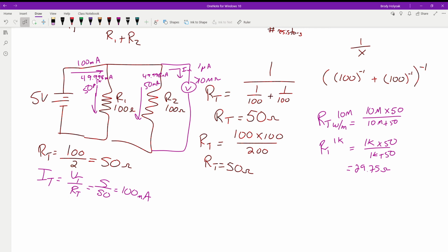So about 1,000 ohms. So if you're on your first setting, that's all the resistance you would have in this guy, measuring your voltage across it. So now you put a 1 kilo ohm load in parallel with 50 ohms, you've cut your resistance down by 40%, which means your current is going to jump up 40%. If you have a fuse or current sensitive parts or power sensitive parts, that could be enough to actually pop your fuse in the circuit that you're measuring. So even though you're taking a measurement, you still can affect your entire circuit and screw it up.